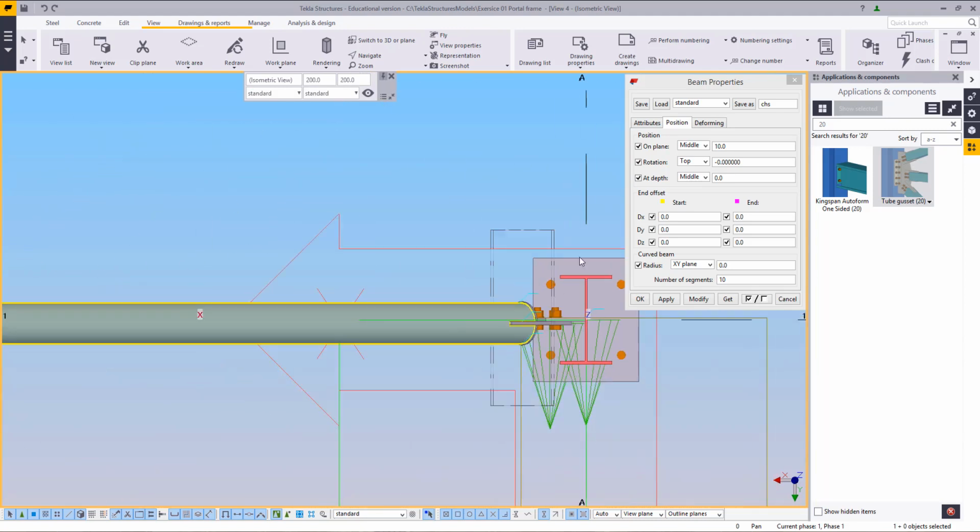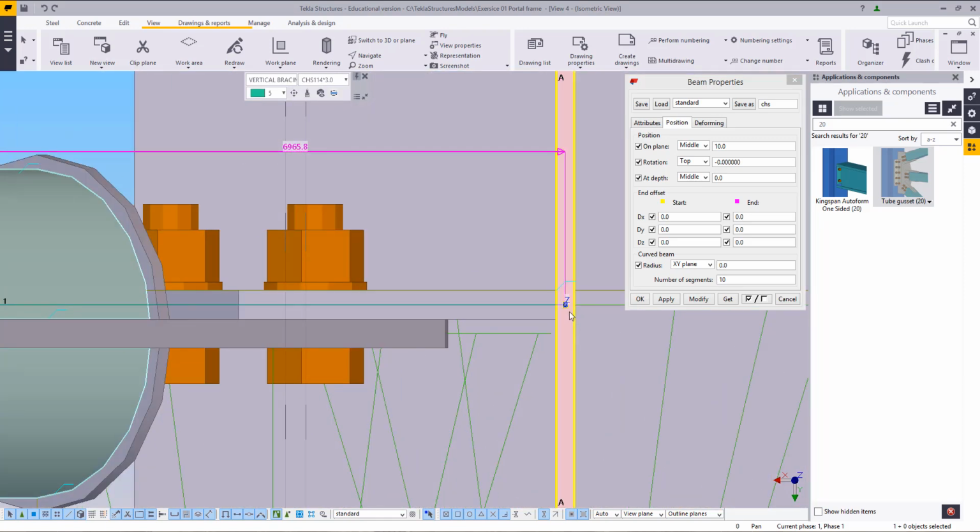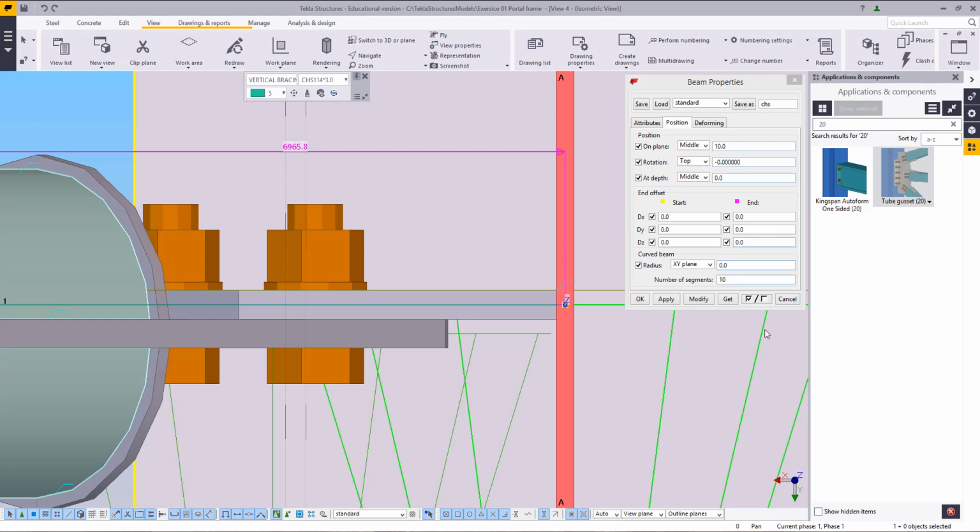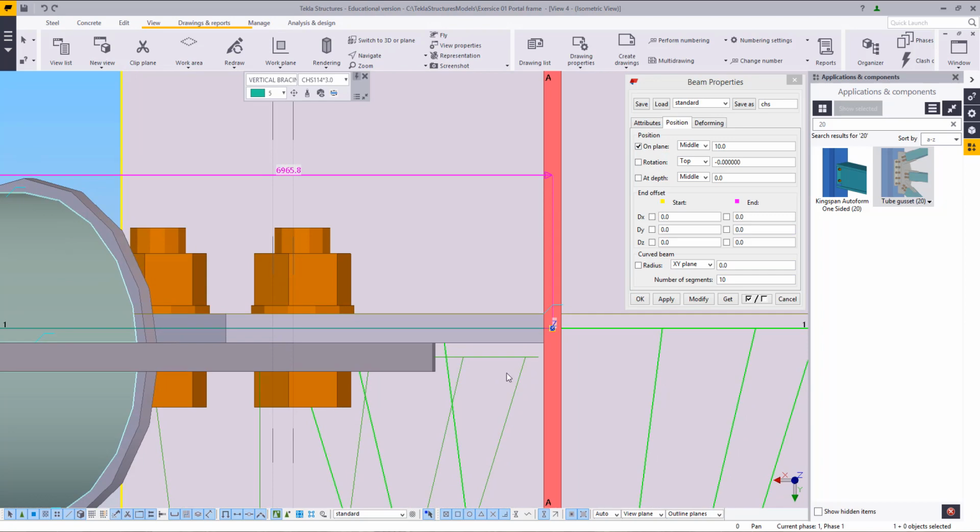Now, the benefit of using position over something like just moving it to 10 to get into the middle is that when you're doing a lot of stuff like trusses that need to come out a certain distance, or even if you're doing floor bracings, using this setting allows you just to select everything, modify once, only that one setting, and you'll know they are all correct.